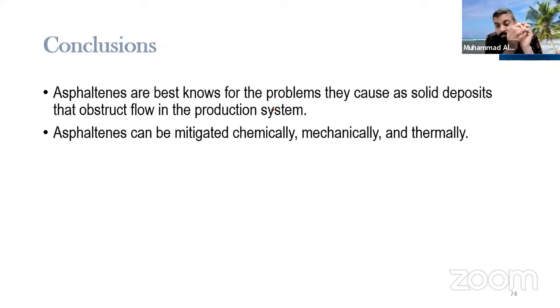Then you have to go to the pressurization test, as I discussed. The effective strategy is to first find out what oil you have, whether it can destabilize or not, then do your pressure testing, then develop your prediction methods, and then look at what you can do with it. And of course, you have to prepare your cleanup procedures. If you see there's asphaltene precipitation, definitely you need chemicals to clean it up, you need pickling jobs and so on.